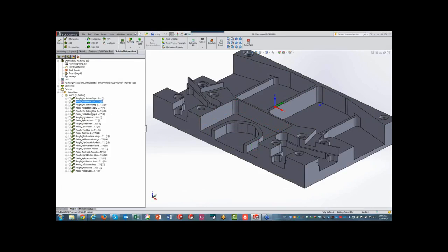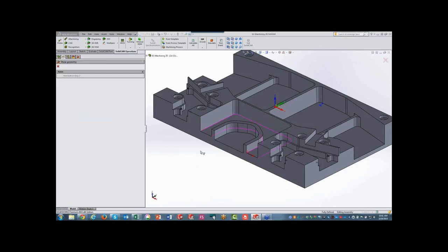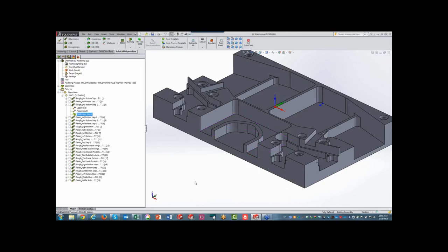The next operation, I had to go down and do, again, the next geometry, which was the bottom step, just like I did in my 2.5D operations. So again, as far as programming time goes, I'm not really saving that much. The only thing I may be saving here is that I don't have to also put in the feed and rate, because that's done automatically with iMachining.